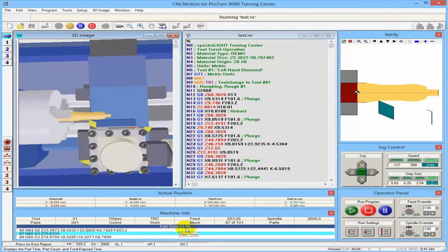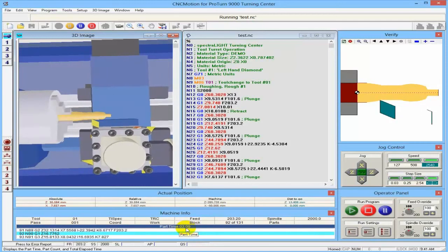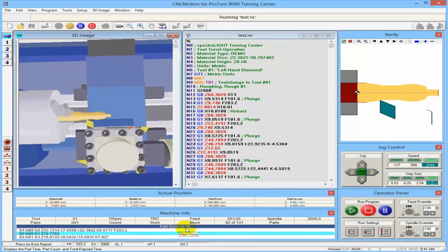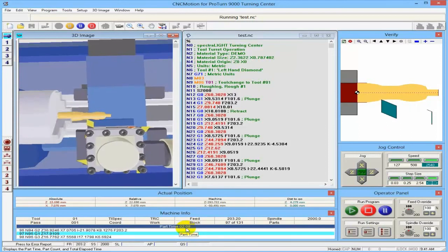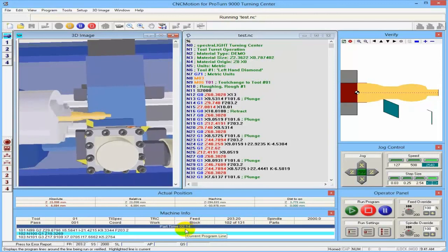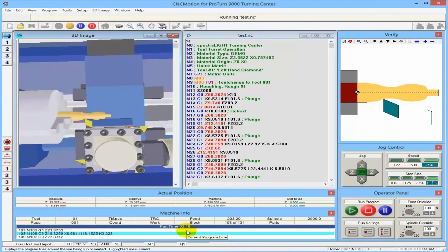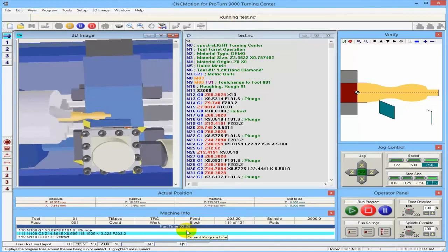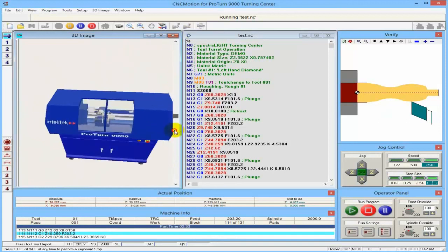It's taking me almost 2 minutes to make about 3/4 of the part. Let's wait until it's finished. I reckon it will be 2 minutes 40, something like this. Now this is important because if you want to produce a lot of parts, you can see the part time before you actually go to the machine, where you can do calculations if it's feasible, if it's making you money or losing you money. Again, all this is done in the simulation software.